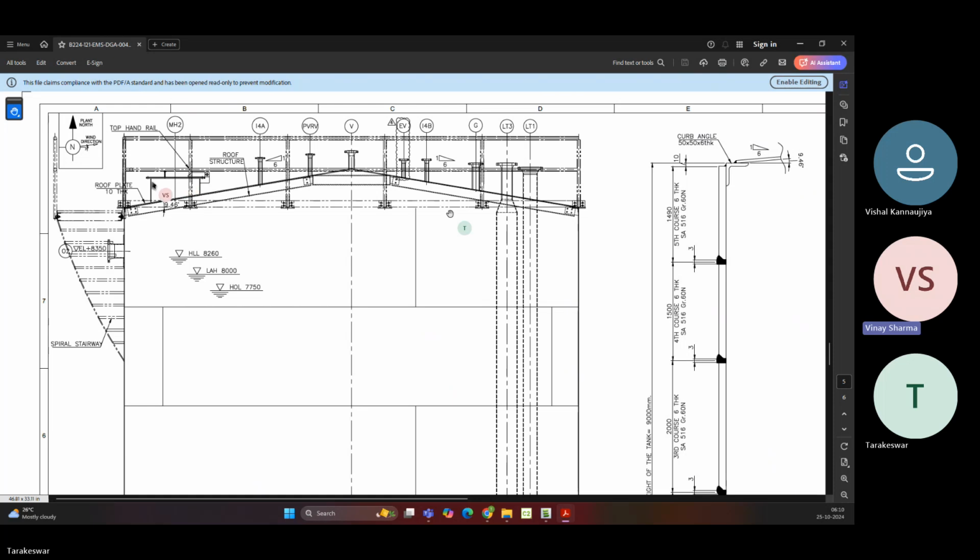For example, the process says that if you put the routing here, it is not feasible or something like that. Normally process does not interfere unless it's a critical line. For example, you route a line from here, and later on you come to know that your pipe is clashing with this nozzle, so you need to change the routing from the backside. I'm just giving an example.